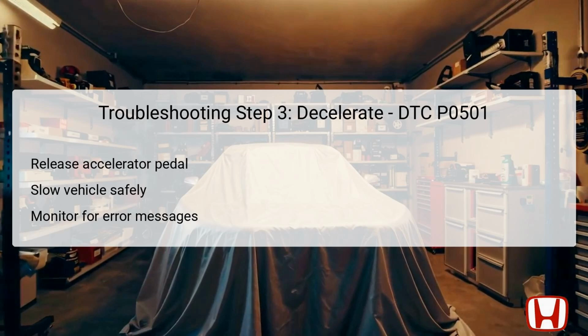Observing any error messages or abnormal behavior from the vehicle dynamics during this process can provide critical clues regarding the status of the CVT speed sensor and its interaction with the PCM. If fluctuations in readings occur, it points towards a fault that needs further inspection.